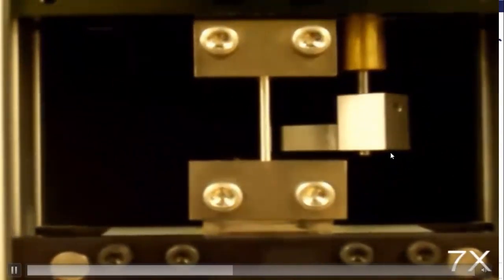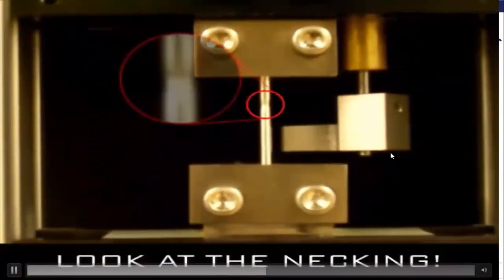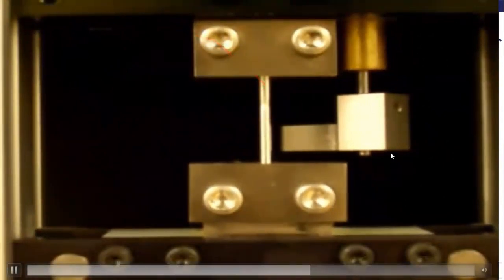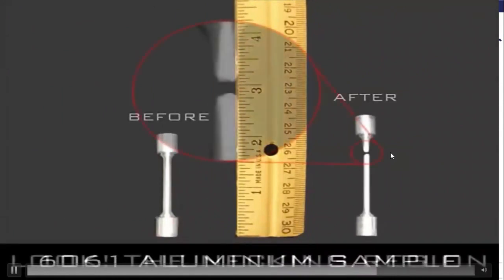Now, initially, we're only seeing elastic movement. And now we're seeing plastic, it is yield and it is necking down. Remember, the planes of atoms pull apart. And we have final failure. And look at the neck down sample. Now we can measure elongation on the right hand side, the stretch, permanent elongation.